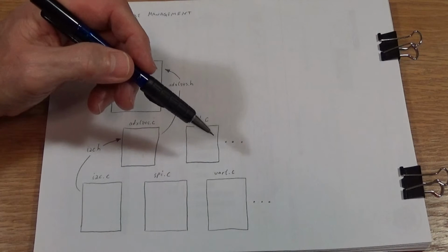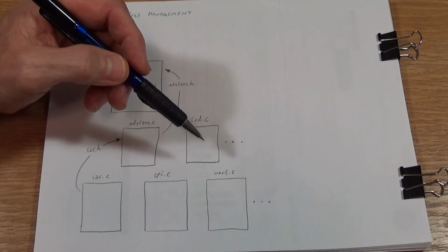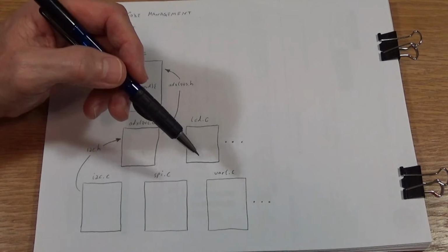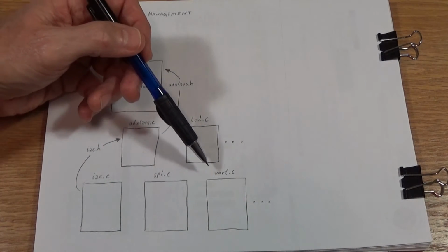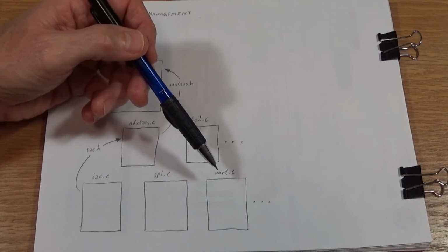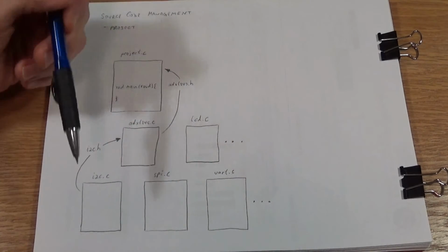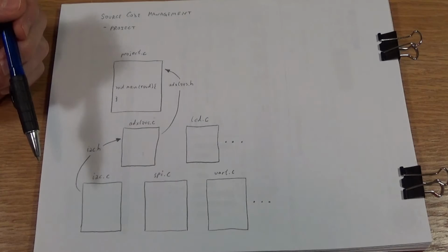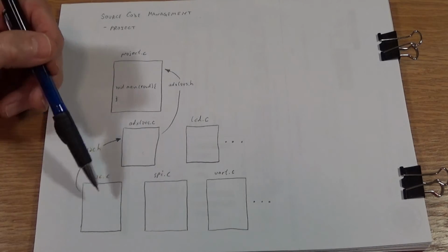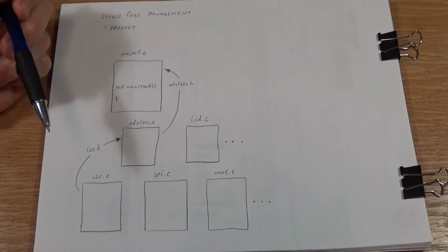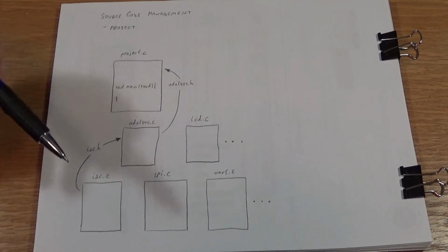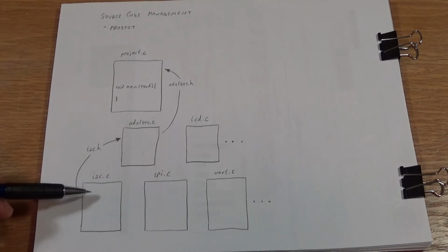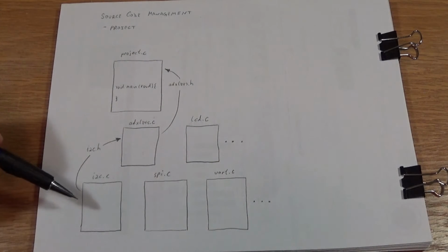And the same with the GPS. It'll probably communicate over a UART, another form of serial port. And again, there's a peripheral inside the microcontroller called a UART that will communicate over that particular protocol. And what you're going to have to do is write software for each of those three different types of serial ports. And what you would likely be doing is that on the next project you're probably going to want to use these things again, but you don't want to have to cut and paste the code.